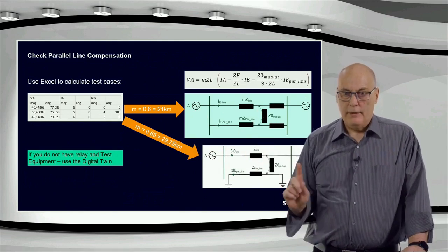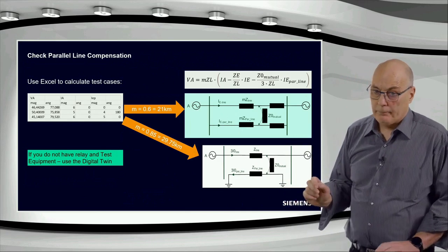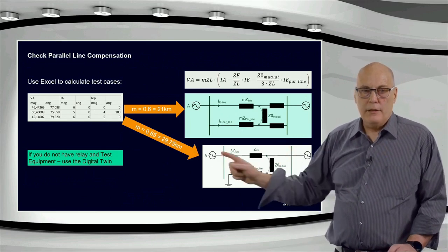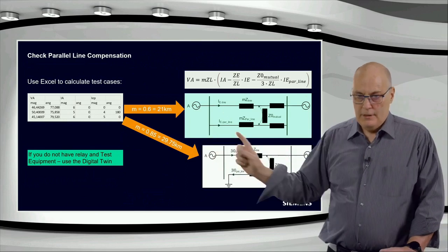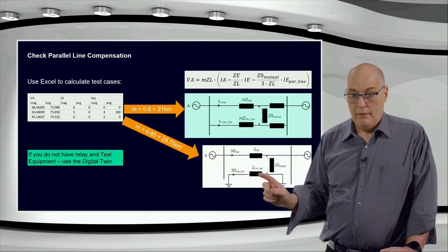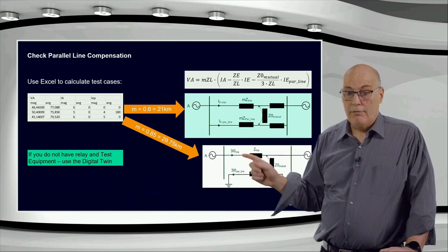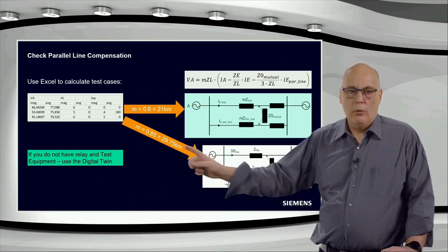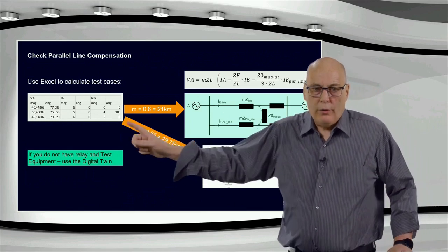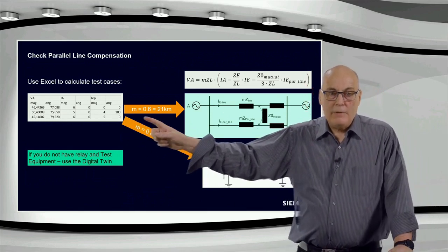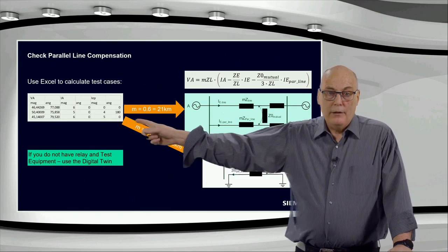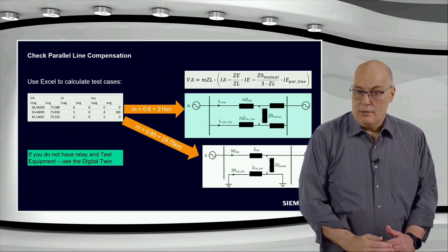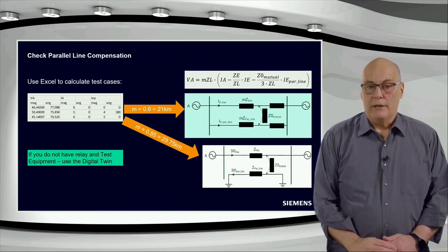And then finally, I did a case for the bottom here. I moved the fault to 85%. In that case, I injected 6 amps on the top feeder and 5 amps in the bottom, but the 5 amps in the opposite direction. And it's interesting, if you look at the voltage magnitudes, although the third test here has 6 amps and 5 amps in the parallel line, you can see the voltage on the complete left is only 45 volts secondary for the third test, although it's larger current.